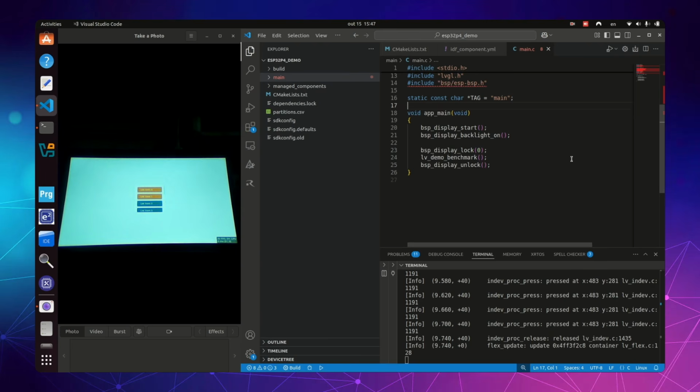Besides the dual core RISC-V CPU, the P4 offers a set of accelerators that could be used for accelerating the rendering of basic shapes, like its pixel processing accelerator and the DMA2D. The pixel processing accelerator is a controller that will accelerate the typical pixel operations that you need to do on 2D images, like blending, copy and filling, and rotating and scaling and doing mirroring of the next object to be